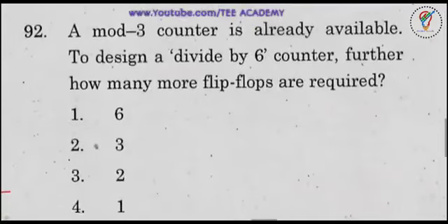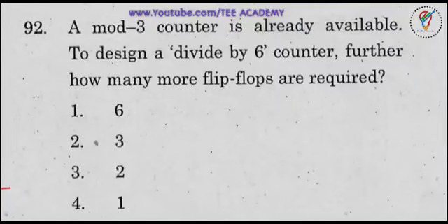Okay, next one. Now this is from digital electronics. A mod 3 counter is already available. To design a divide by 6 counter, further how many flip-flops are required? First of all, for a mod 3 counter, how many flip-flops are required? For a mod 3 counter, we require 2 flip-flops.